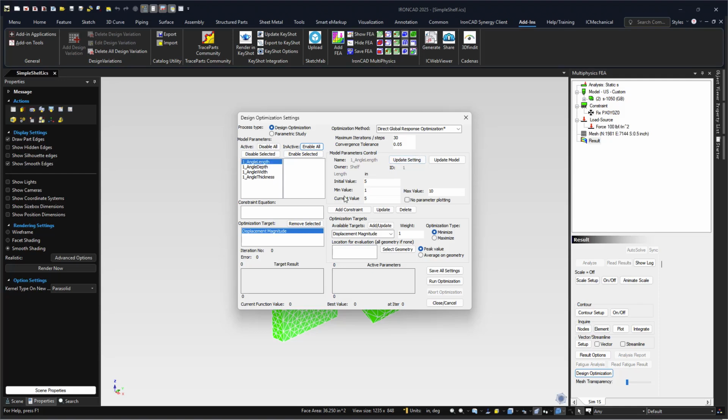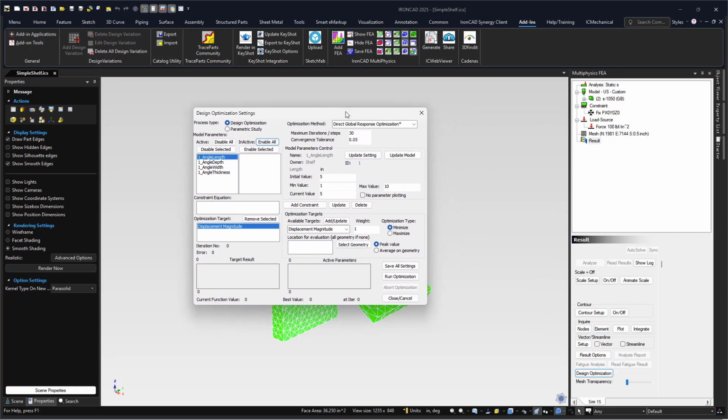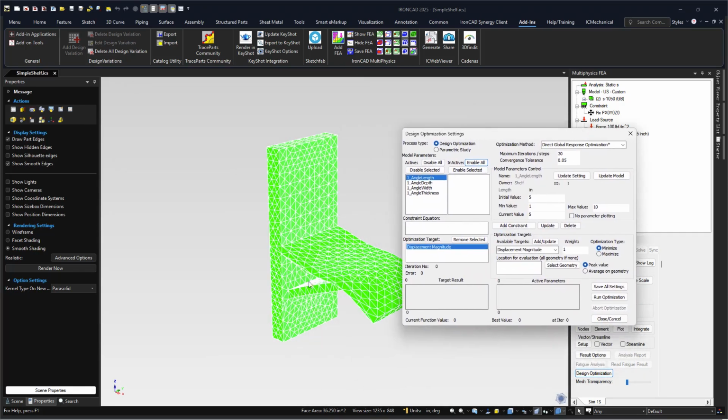Next, you want to set your initial and your maximum value for each parameter. So in our case, I'm just going to move this over so we can see this here. Our length again is from here to out here. That's what our value was for that. So what we want to do is set what the initial value is. It doesn't really matter much. You can use that as the starting point, but you can adjust that to start at a smaller one, work its way up, or set it halfway, however you like. It's up to you. But what we want to do is set the minimum value. We'll say for the top edge, we want it to only go in maybe a minimum distance from here of 2 inches, and the maximum on there is about 7. So let's go ahead and set that to 6 for that maximum length.